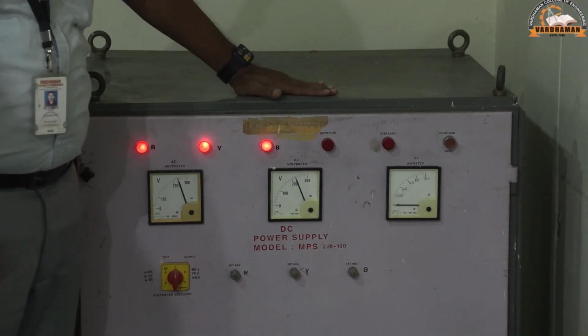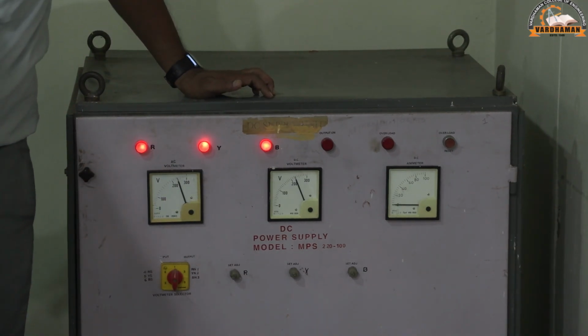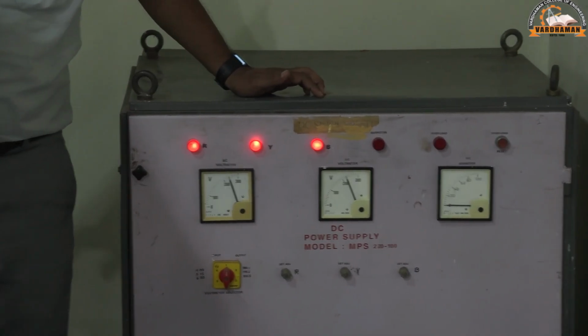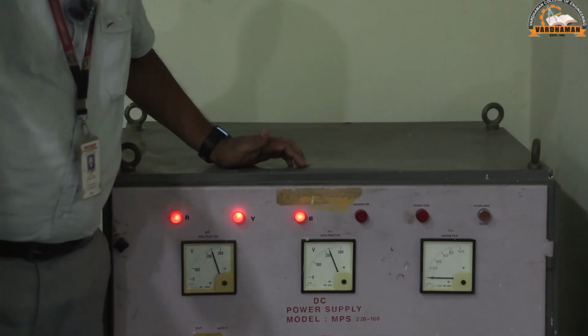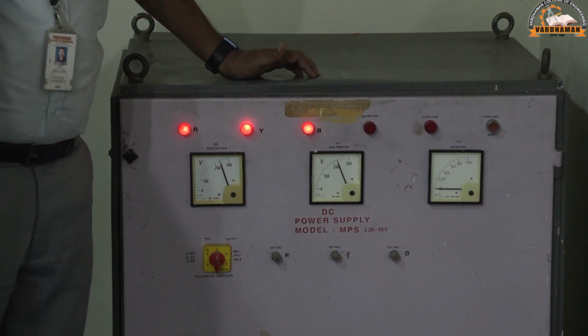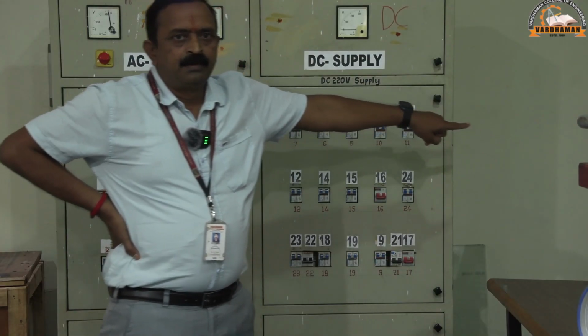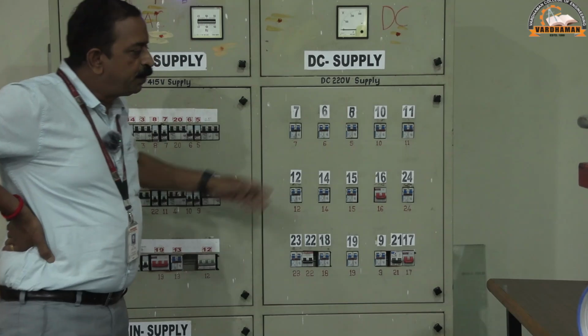This is about the rectifier. From this, again, the main supply is taken to the mains of that DC section, and from that it is distributed to the individual MCBs. From the MCBs, it is taken through this channel towards the panel wherever the DC motor is erected. The rectifier is going to convert three-phase voltage into DC voltage.